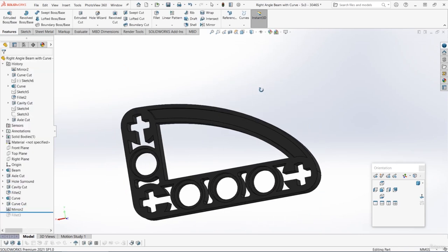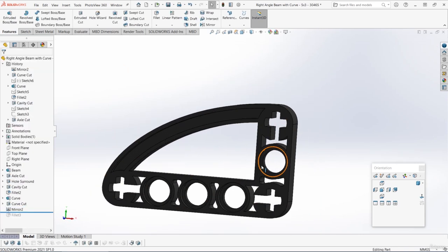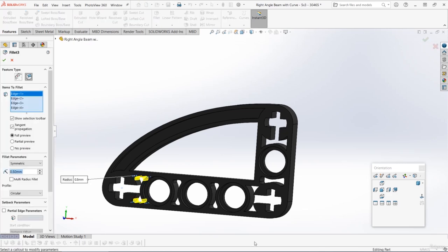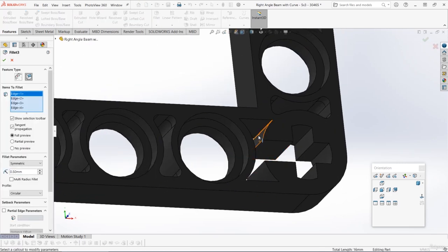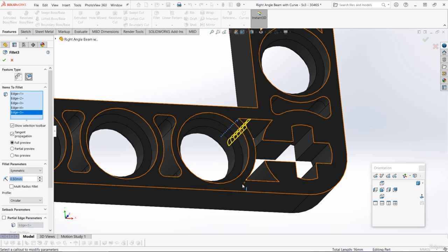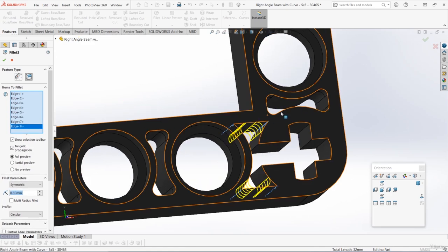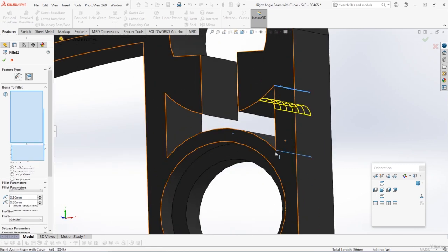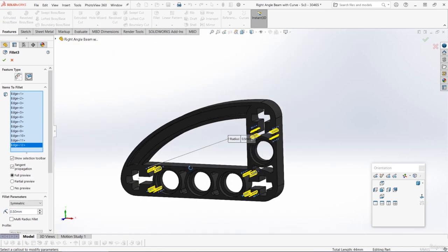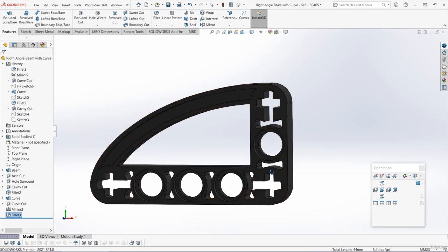And then the final thing to do is just add in the remaining fillets. So let's drag down below that final feature, and then we've only got the fillets on the left, so let's edit that feature, and let's add the remaining 8 fillets. So there's 4 here, and as we add the one in the top right corner, it gives even more material there. And then there's a final 4 up here at the top.